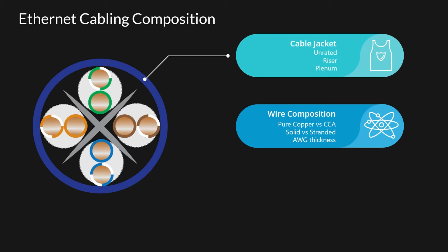basically 2 different types of cabling. There's when these intertwisted pair, they can be solid copper, and that's meant for structured wiring. If you're putting it in the walls and it's not going to move around a lot, then the solid cabling is the better way to go because it conducts better. But patch cables, if you go out to the store and buy an Ethernet cable from an office supply store, and you're like, oh, 15-foot Ethernet cable, that is actually made out of stranded cabling.